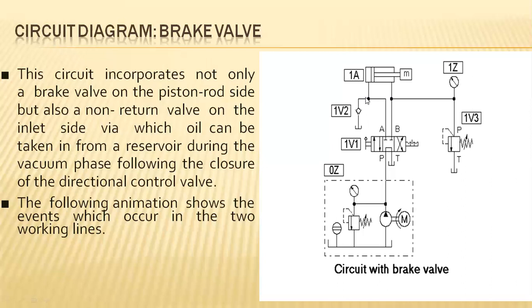At this particular junction it acts as a bilateral movement, towards this direction and towards this direction. Nominally, the pressurized fluid tends to move in any number of directions available to it. But here we are placing this check valve or non-return valve, which doesn't allow the fluid to flow back to the oil reservoir. It has only one passage of movement, connected to the second position, which will drive the fluid to the oil reservoir.